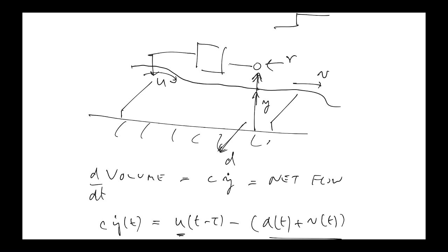So last time we talked about modelling, okay, for the purposes of control design, and we saw that we can get a good model for how the water level at the downstream end of a so-called pool, a stretch of water between two regulating structures, depends on the flow in to the system and the flow out, which includes a local load and downstream load. All right, and that model looks like this.